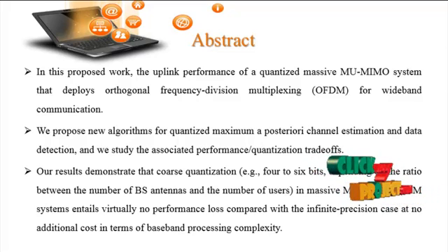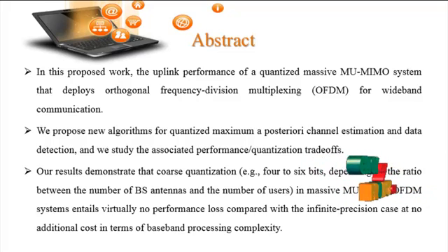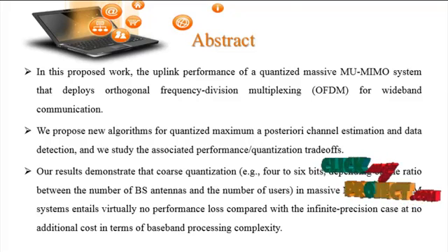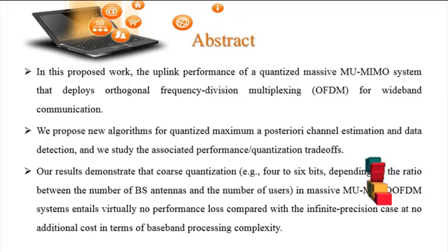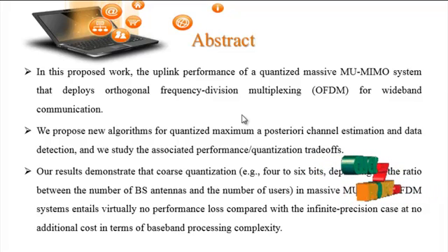The theoretical limits as well as practical transfer algorithms for such quantized multi-user MIMO systems operating over frequency-flat narrowband channels have been studied extensively. However, the practically relevant scenario where such communication systems operate over frequency-selective wideband channels is less well understood. So in this paper, we investigate the uplink performance of a quantized massive multi-user MIMO system that deploys orthogonal frequency division multiplexing for wideband communication.